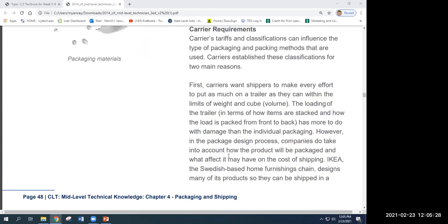And it talks about loading, that the heavier items are put in the front of the trailer. And so if you had to stop, something heavy in the very back wouldn't be pushed into some lighter weight items and crush it. And it's nice to have that weight over the hitch, the 5th wheel up in front, just to make sure that you got a good, secure, heavy load over it. The second place that there's heavy loads is over the axle, and that's to help with traction. And it helps distribute the weight more if it's between the axle and the front of the trailer.